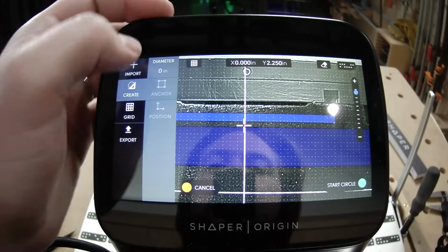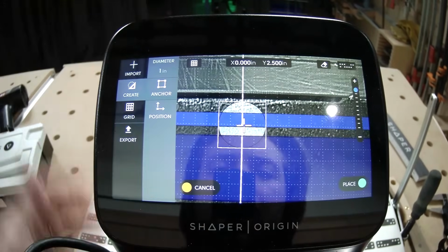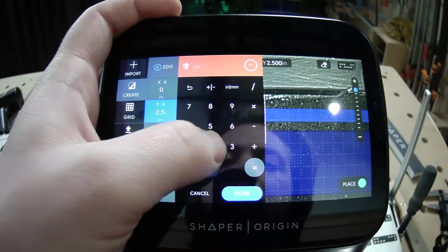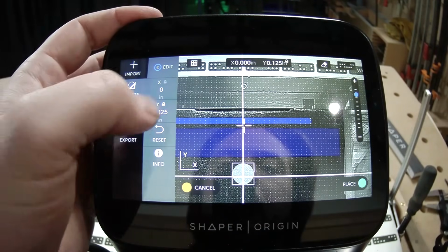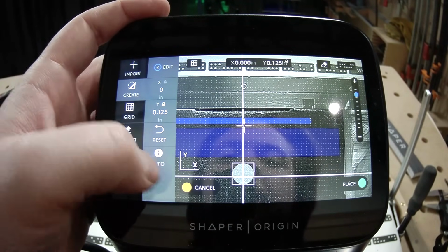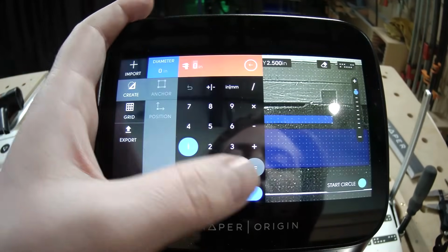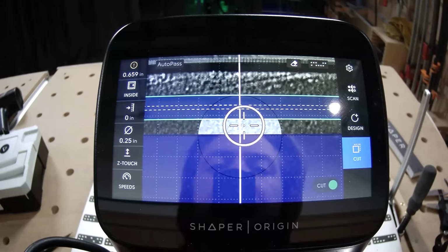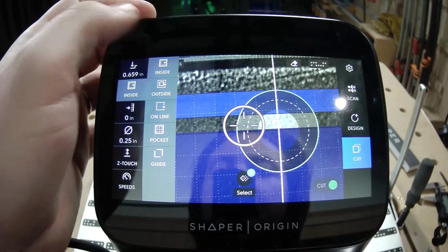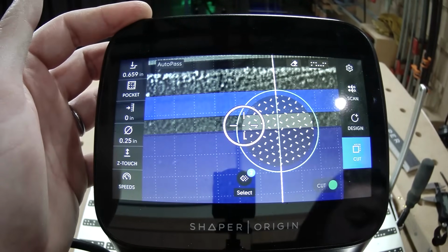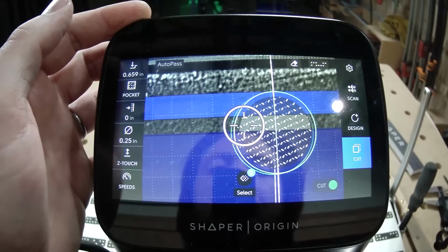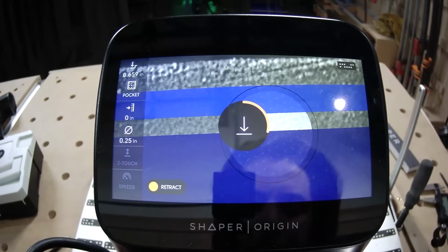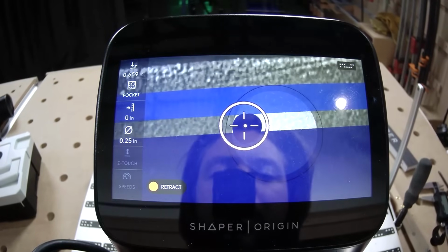All right, so we're going to create a circle. Just something like 1 inch diameter. I want to go up 1.25. Whoop. Wrong direction. That should be sufficient. Yeah. Just a little something in between. And again, do a pocket first. Could go down to that same depth. Yeah? Of the ruler? Yeah. I like that. All right. Just a quick little pocket to clear this out.